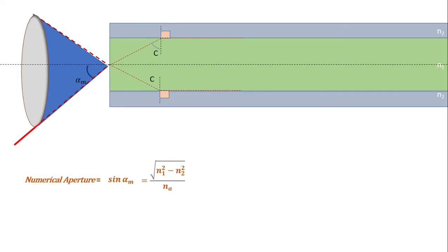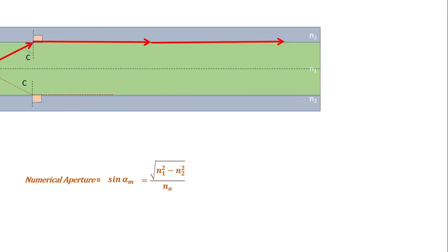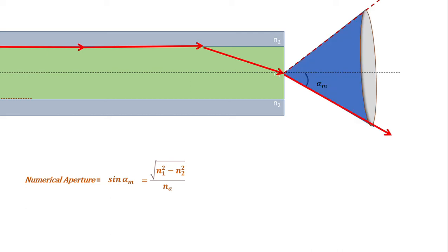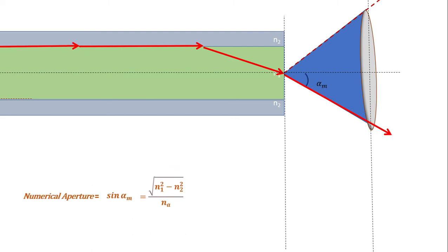In this experiment, we use a screen projection method to estimate the fiber acceptance angle alpha m. This depends on the fact that the acceptance angle at the entrance of the optical fiber is equivalent to the angle of exit of the fiber. The emergence cone of the optical fiber on projecting to a plane surface develops a trace with a disc shape. Let the trace be made at a distance L from the tail of the optical fiber. The radius of the disc be r.